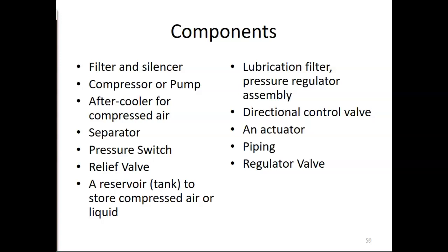Everything dries out, everything cracks, everything starts to bleed, right? If you don't have oil in an air system, everything's just dry. What's going to happen to your seals over time is they'll deteriorate faster. Your components will deteriorate faster. So what do you do? You add just a drop of oil every now and then. It vaporizes into the air and it finds its way to each component, and hey, it's lubricated, everything's good. It lasts longer that way.